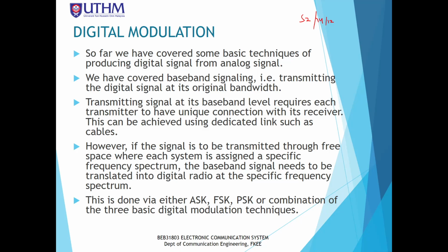Now, if we want to transmit into the wireless medium, we need to modulate the digital code word with the analog carrier, so that we can produce an electromagnetic waveform at a higher frequency, in radio frequency, suitable for transmission. In this case, it involves modulation, and we convert the low frequency into high frequency.